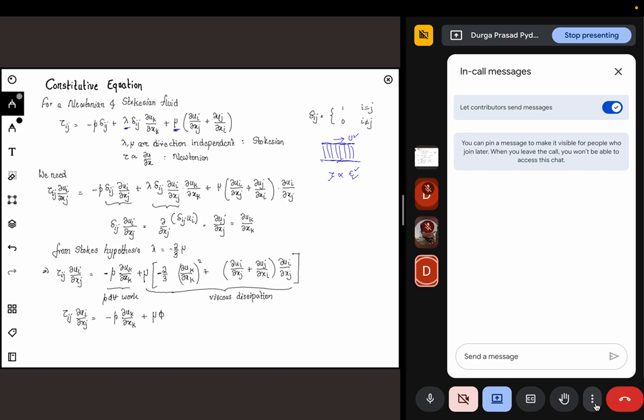So in a similar way, for a fluid, all we are able to measure is velocity, and we are trying to get the stresses from the velocity itself. And in order to do that, we will not be able to do it unless we know the relation between stress and strain rate. Like in solids, we call it strain; in fluids, it will be the rate of strain.